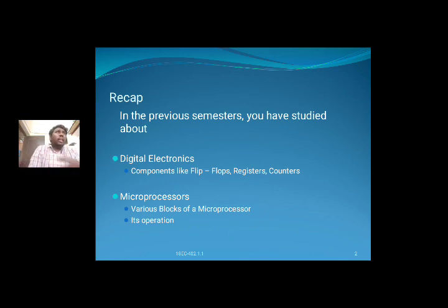But in a microprocessor, the external memory will be used and all the ports are not programmable. And if you want to interface some external devices to the microprocessor, there is a deficiency of programmable ports, that means programmable ports are not available in the microprocessor. And if you want to execute more programs in the microprocessor, memory problems will also be faced. That means the memory is not inbuilt in our particular microprocessor. That means memory is externally connected to the microprocessor.